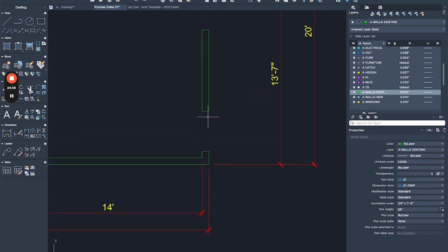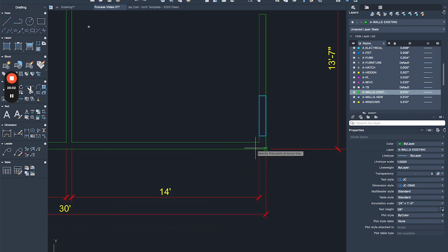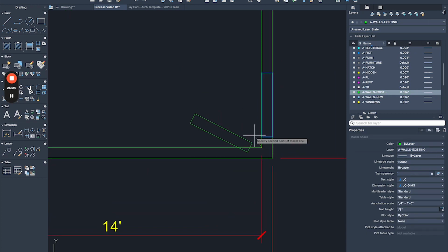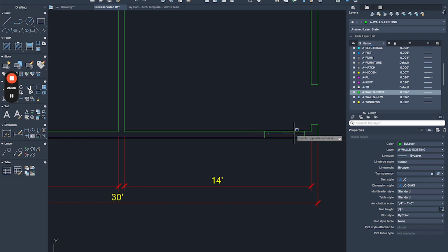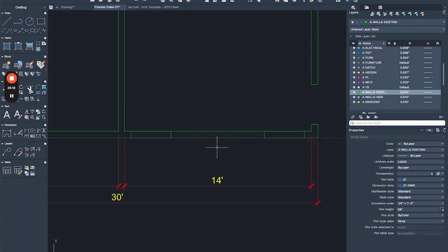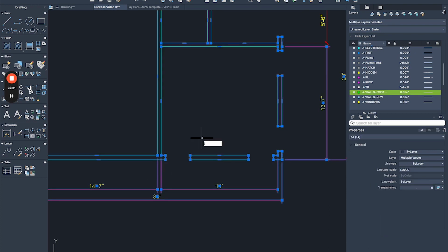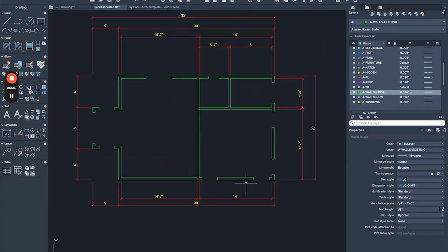Okay, this is cool. So I'm gonna do the same window size, but on the opposite wall. So I drew this reference polyline, and then I'm gonna mirror it. Then I'm gonna erase it because I didn't want it. And then this, I can just mirror it because that's my plan to do this floor plan, is literally to have two windows here, two windows here. They're all same size at 3 feet. And then I'm gonna trim the whole thing, join the whole thing, and this will make sense once we get the hedge. Right. So for windows, I think I'm happy.